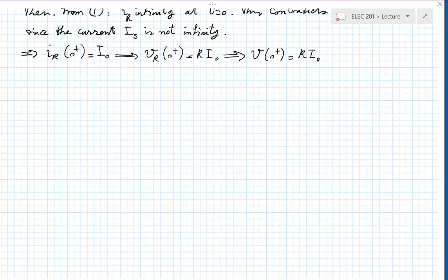So if you're lucky enough and there is enough leakage and the current source is well designed to protect itself, namely, if it sees that it's trying to change things quickly, but the voltage across it is developing rapidly, it won't do it. It will have a protection mechanism, a control circuit that will say, I'm not going to change rapidly. Okay?